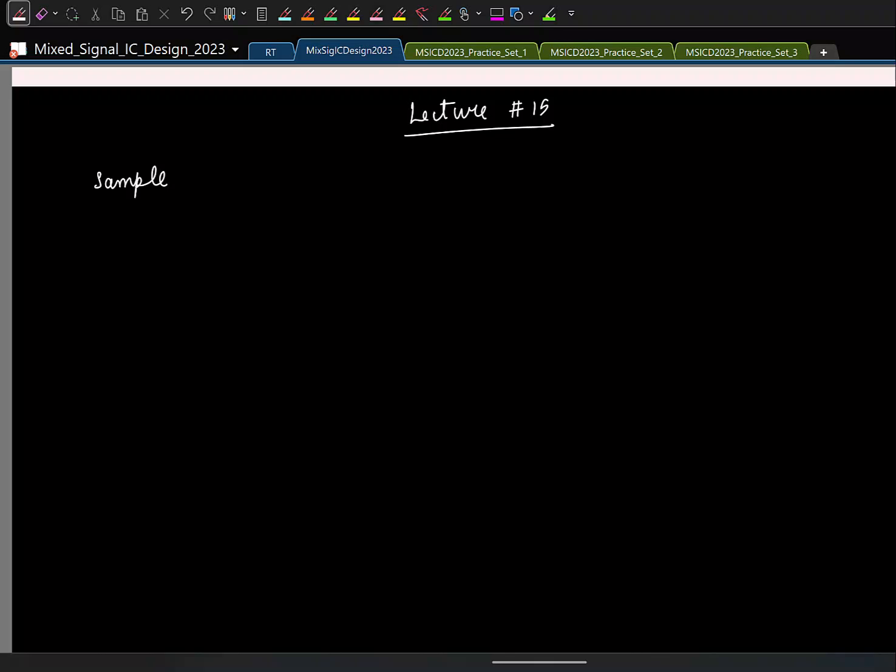We compare with the zeroth reference voltage, and then let us say if it's an n-bit SAR, how many times will I have to do the comparison? We have to do it n times. So we have a total of n comparisons. Is it always n? So totally we have, let's say, n plus 1 operations.